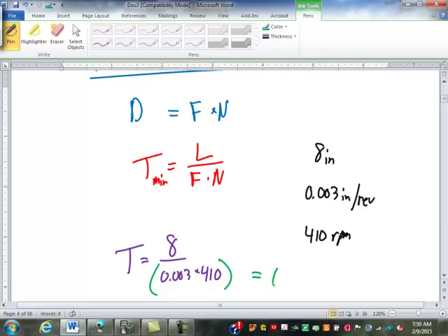6.5. That sounds better. What period of time is that 6.5 in? That is minutes. Not inches, just minutes. Well, an 8-inch cut is a pretty hefty cut. I mean, 0.003 per revolution is a small advancement, but if you're going through steel, that's not off.